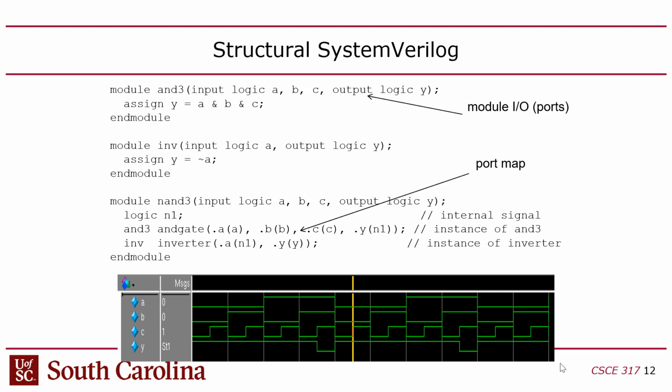Now, you can put in a test bench that pretends to be the Nios processor, right? So you could create a test bench that generates Avalon transactions. So the peripherals in this class are going to be Avalon slaves. Well, they could be Avalon masters too if you want, but we're going to be designing a slave because we're designing a peripheral for the CPU, right? So to test that, we would need some master to come in and do an Avalon transaction, right?